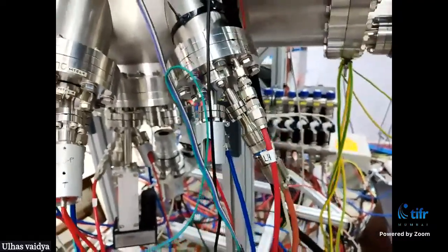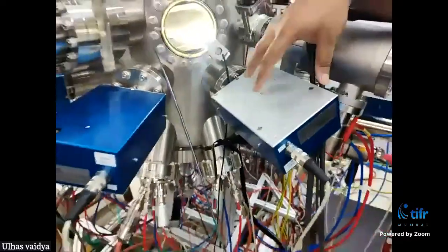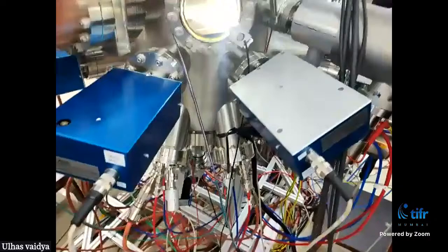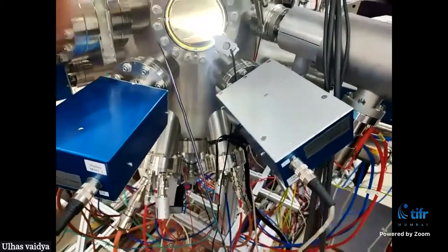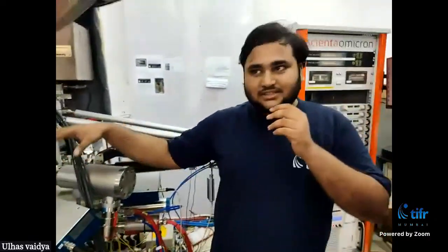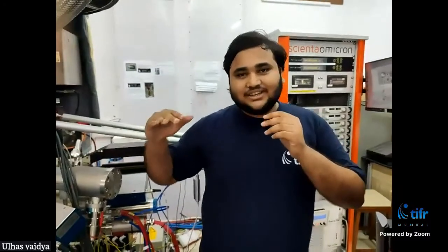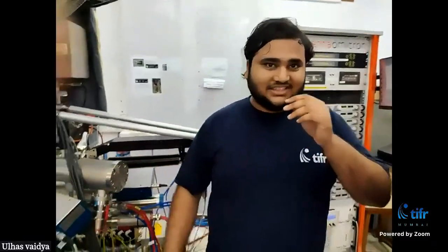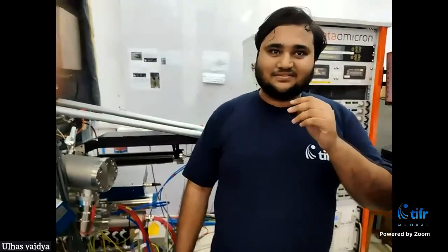And you can see here, everything has a separate shutter. These things are actually shutters. So we can control exactly when we want to let some atoms go and make something using the shutters. And that is why we can go layer by layer, atomic layer by layer, using these shutter controls. When you want to evaporate some material and send it to the substrate, you open the gate, and then you can close it.